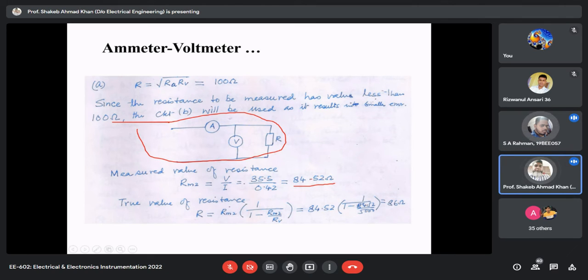Which is more accurate, if I take an analog meter or a digital meter, sir? You cannot say like this. Again, I'm telling you, it is not technology based. It all depends on how these two meters are made and what accuracy the manufacturer is claiming. Your digital instrument may be plus minus 2%, and your analog instrument may be plus minus 1%. In another set, your analog may be more accurate than your digital one.